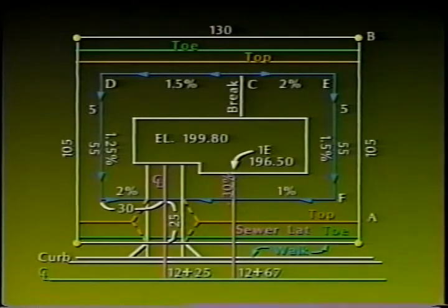After question 2, question 3 is a breeze. It asks for the slope from point A to the toe. We know the elevation of point F at the flow line of the swale from our work on question 2, and the fact that the top of the slope and point A are 1 foot above the flow line from the plan. We've already computed the back of walk elevation at the southeast property corner for question 1, so we know the change in elevation.